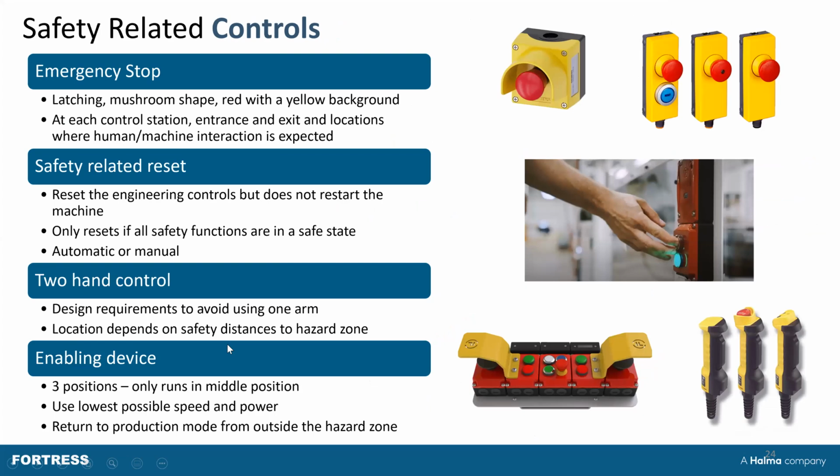And then our last bit on controls and devices is that there are a lot more safety related controls to consider as well. There are going to be requirements around each of these, and each of them actually has its own standard with all of those requirements in. Emergency stops you'll be familiar with, but there are specific requirements on not just the shape and the color, but also where they are and how many you need in different areas.